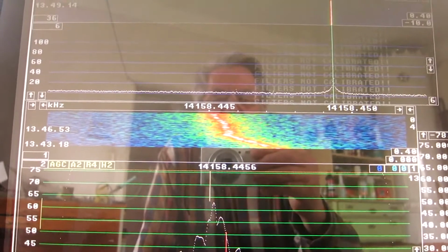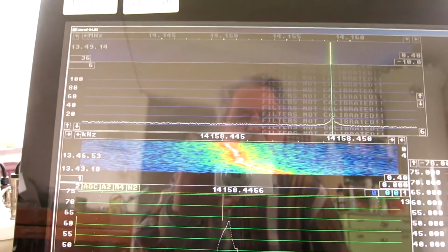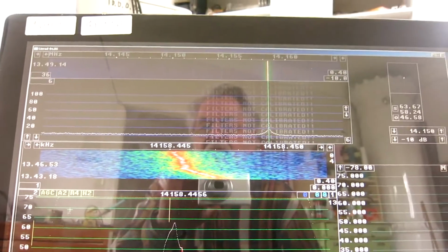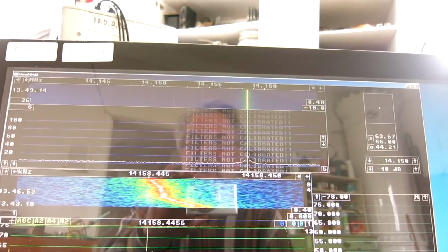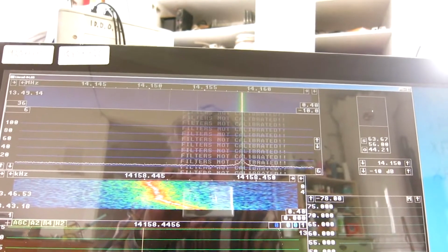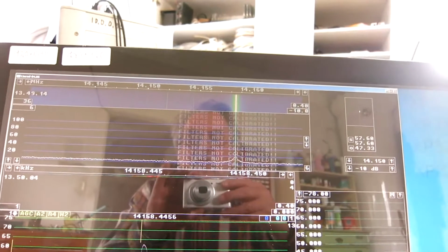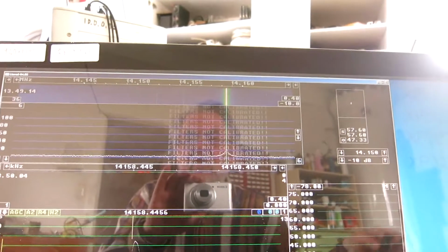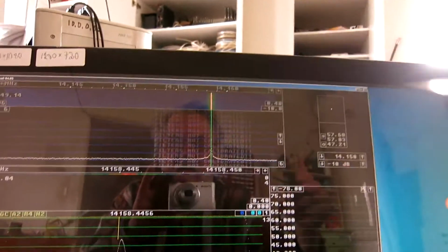To see the slope on the noise floor, I can increase averaging. It's now 2, and I make it 10. Which means it will average over about as much as the height of the fonts here.